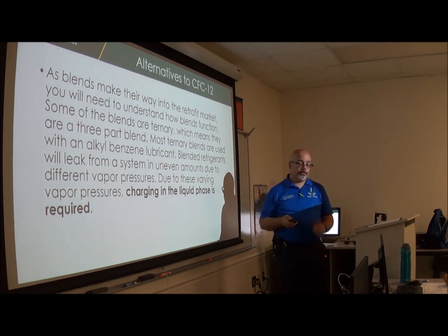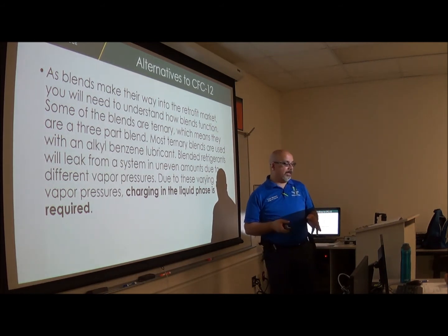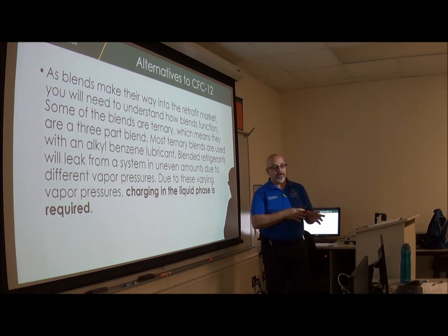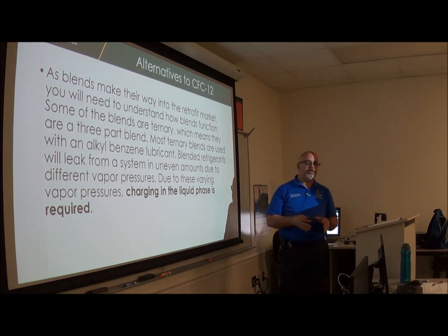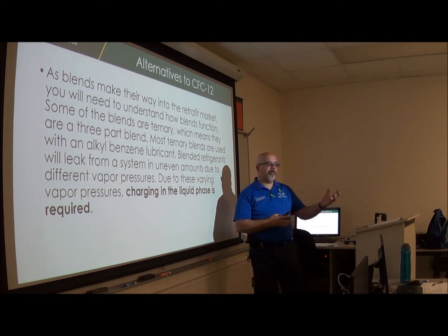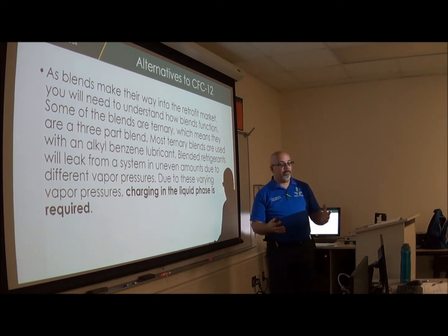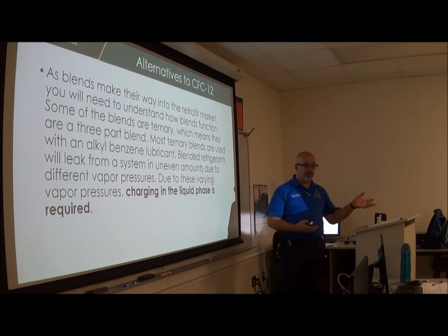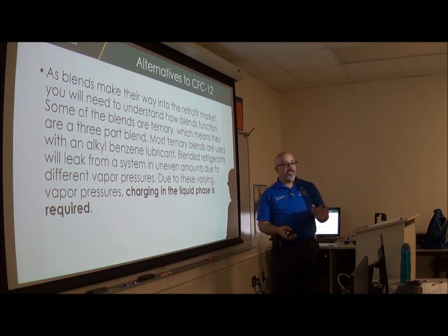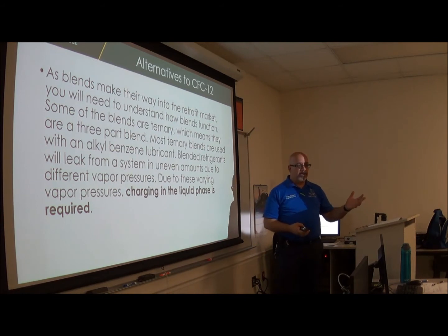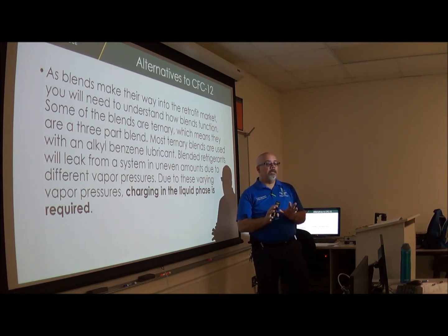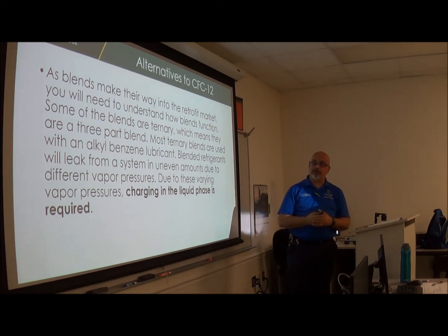Alternatives to CFC-12. There has been an issue from when R12 was eliminated and we came to R134A, which in places like China, they come out with these blends which still have R12 mixed with 134A, maybe even mixed with R22, because they're not recycling them like they're supposed to. So those are the famous blends that I'm going to talk about here.